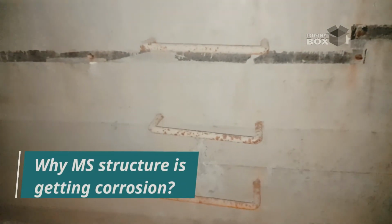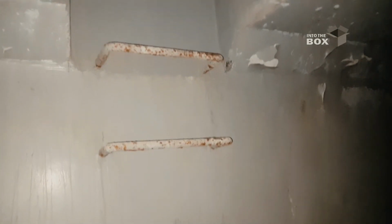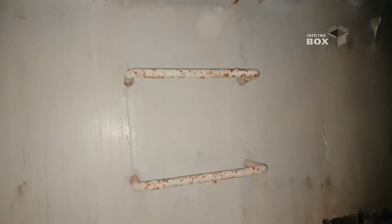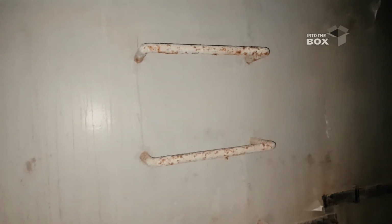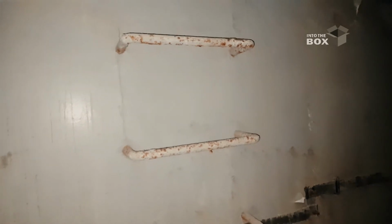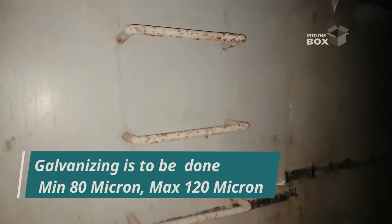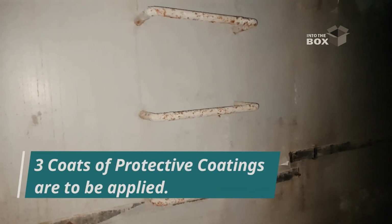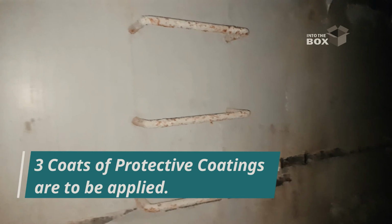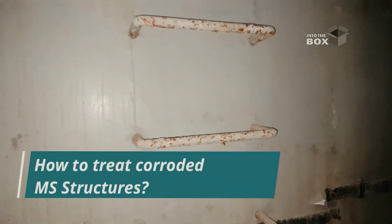Our next target is the MS structure. Here you can see there are access rungs in order to access through the manhole. These access rungs are made of MS, mild steel. One important factor one needs to account for while dealing with mild steel in substructures is that they all need to be galvanized and coated with the protective coatings available in the market. But unfortunately, there is some lacking in this, and that's why it has corroded.